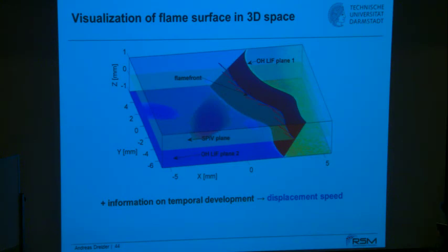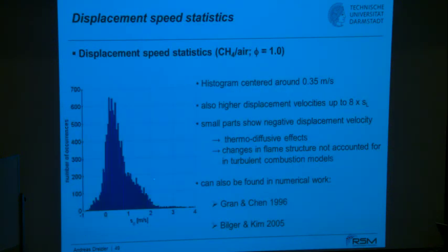Which as well has a certain influence on that. Yeah? And that needs to be accounted for, such that the interpretation of these histograms is maybe not that easy and straightforward. So negative flame speed does not mean negative consumption rate. Yeah? You're not producing fuel out of water and CO2. I think that's clear. Yeah? That would be great. It is as well dependent on where you have your isoline and measure that. Yeah? This is dependent on that as well. And this is given here, as I said, by the velocity taken at a certain distance from that, as well as where you track your flame front, which in our case was the maximum gradient of the OH. So if you would do that in a different isoline, that can be easily done in DNS, not so easy in experiments, you would find a changed histogram.